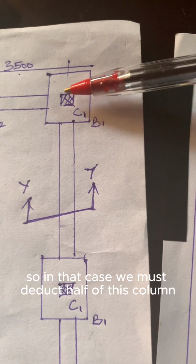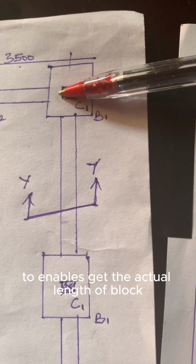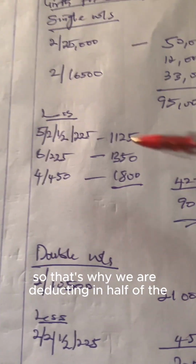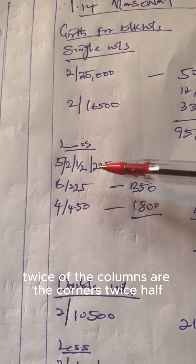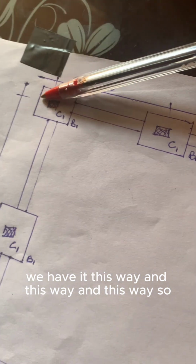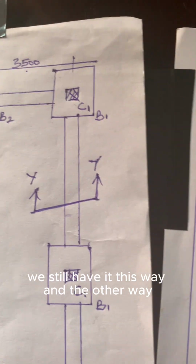So in that case, we must deduct half of this column to enable us get the actual length of block wall, which stops at the edge of the column. So that's why we are deducting twice half of the columns at the corners, because we have it this way and this way and this way. And for the other width, we still have it this way and the other way.